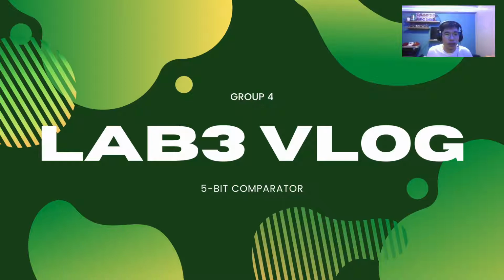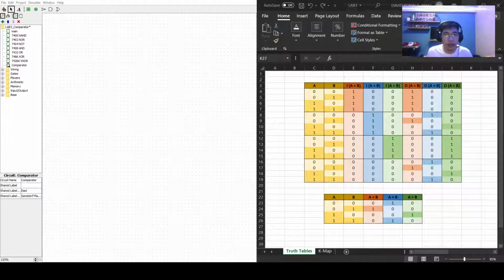I'll be using the Logisim application as well as Excel to show my given variables. Here we could see that I've created a truth table. The one below is a 1-bit comparator truth table. As I've said earlier, two inputs, A and B, will give three outputs: A less than B, A equal to B, and A greater than B.